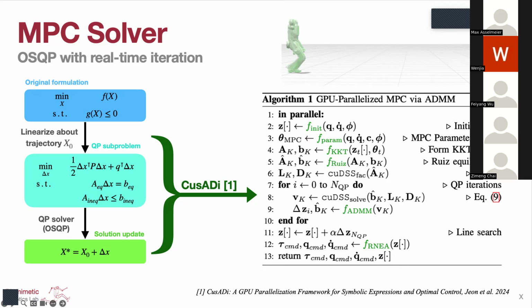But on the other hand, I'm taking the opposite approach, where let's start from the opposite of soup, very discrete ingredients, and slowly build on top of that so we can clearly look at what our torques are doing. In terms of scalability, the direction that I want to go in is trying to leverage this kind of MPC, but not in such a separate way where I directly add these torques together. Rather, now that I have this architecture and this parallelization set up, can I incorporate diffusion or imitation into this loop? Can I feed the torques of the MPC into a lower level policy that can then make these really robust?